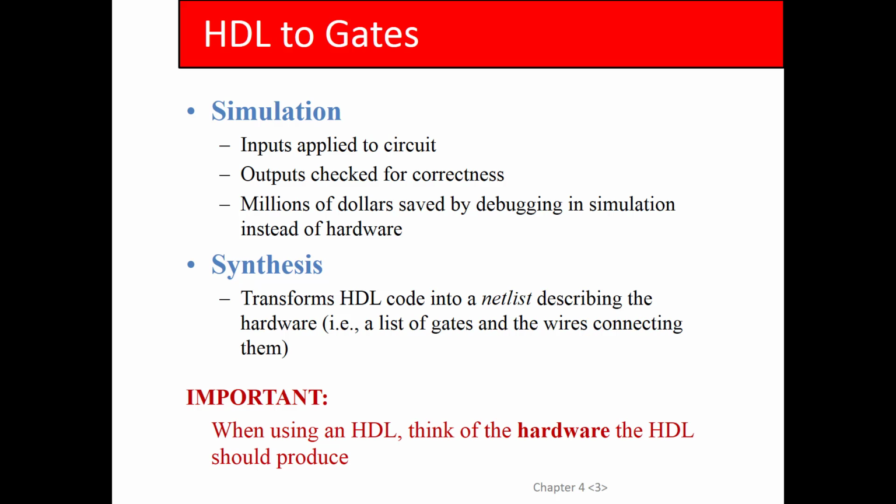Synthesis is where, just to clarify, if you design something in Verilog or VHDL, you can simulate it, and it'll give you a waveform just like we had in the last test, right? That's the way you tell if it's working, and debug it if necessary. But at some point, you're going to say, oh, this thing's working, time to generate hardware. Then you do synthesis, and that converts your program into wires and gates, right? I don't think there's any way to do this for free. This costs big bucks.